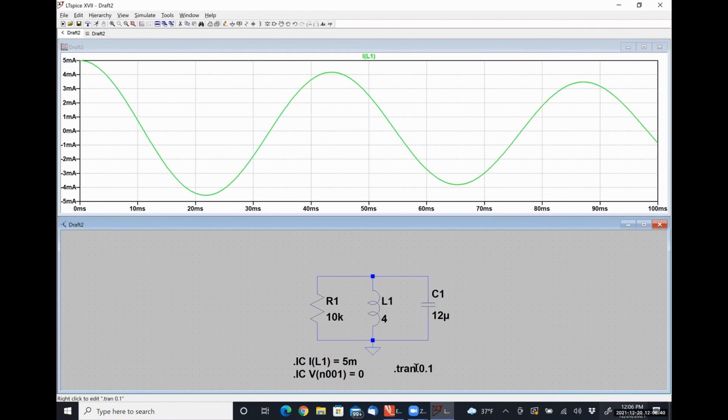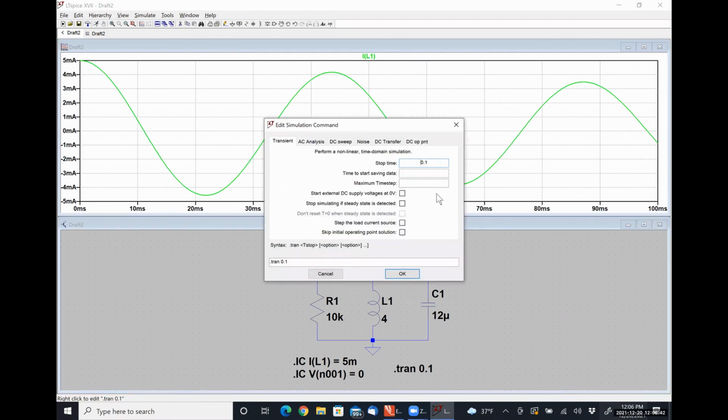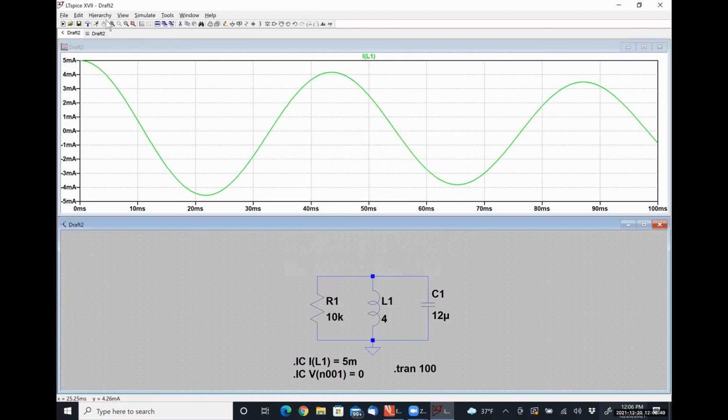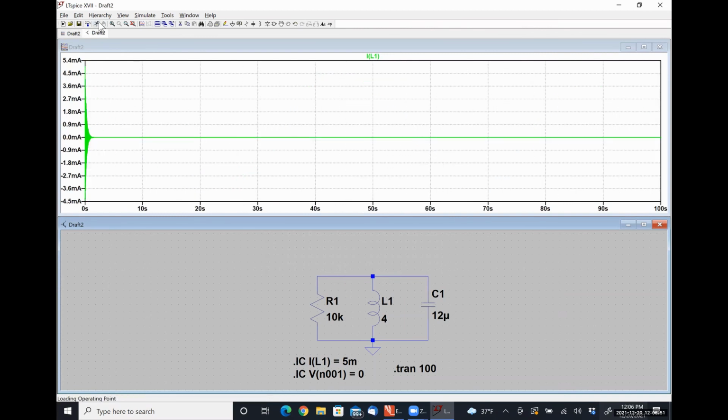Similarly, if I did it for 100 seconds, that isn't good enough because I can't see what's actually going on, okay? So you're going to need to play around with the length of your simulations to show me an accurate representation of what the circuit's doing without including a bunch of dumb stuff that doesn't really tell me anything. All right, so let's go back to 1.5 seconds.